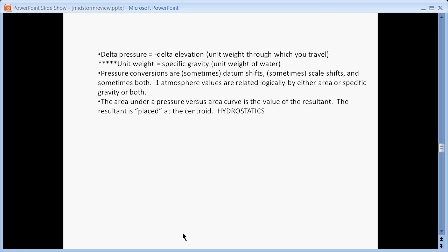Sum of the forces equals 0, sum of the moments equals 0. We looked again at free body diagrams, understanding that we have to account for gravity, which is quote-unquote touching, or electromagnetic force, which is quote-unquote touching, but we also have to account for everything that is actually touching it, including fluid interfaces such as water or air, which are distributed, just like weight is distributed over the entirety of something that has mass.